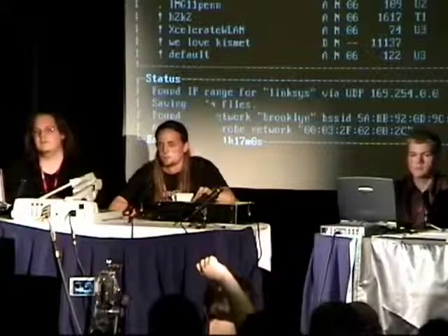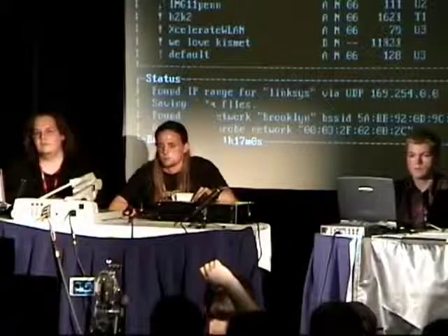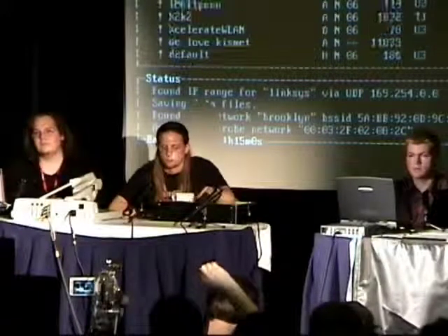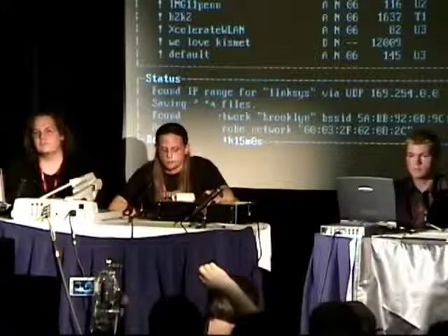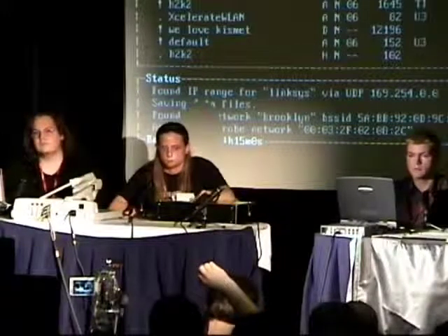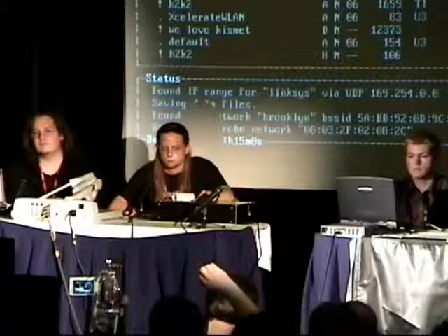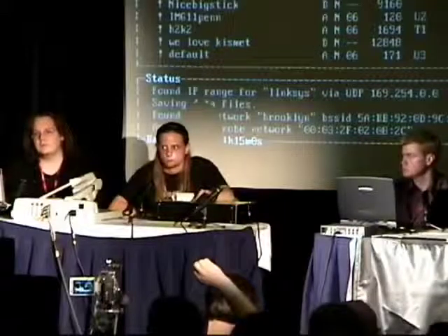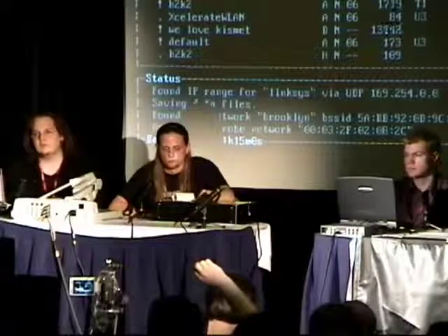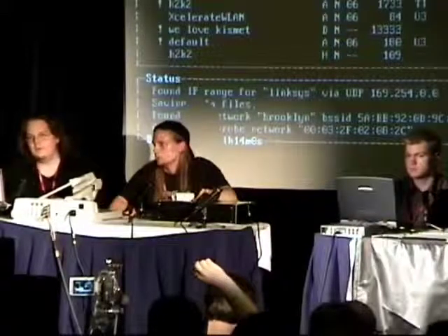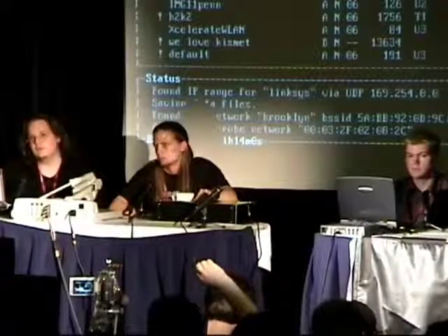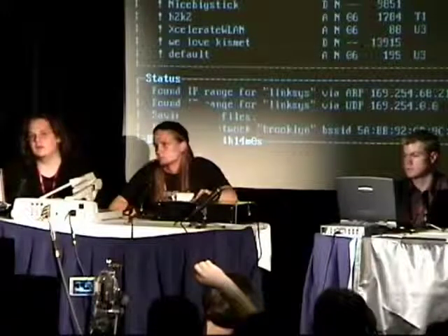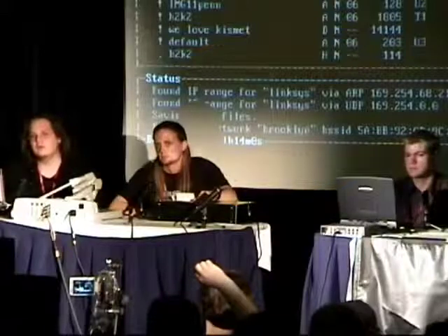A second thing, I know this is sort of the opposite direction from what you've been talking about, but if I wanted to take an external antenna mounted on my roof, leading down to my wireless access port to try to get the 802.11b signal out further, is that possible, and if so, what would you recommend to try to do that? Is it an antenna booster, or a particular type of omnidirectional antenna? Do you mean to transmit it further or receive from further away? Transmit it further. Your best bet would be a directional, but we could probably talk about that at 9 o'clock at the workshop. We can answer more specific questions like that.